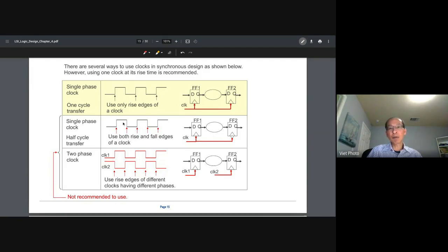The duty cycle can be only 40%, 50%, or sometimes 70%, because when the clock goes through the inverter, it swaps the status, 0 to 1 and 1 to 0. So in one node the duty cycle might be 40%, but at the next stage it will become 60% and 40%. It really messes up the timing data.